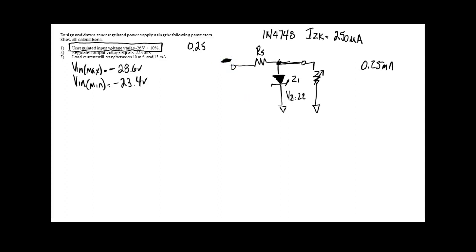To bias a diode, we need to put the negative toward the cathode. Well, here's the cathode right there, Brandon. So we're putting the negative toward the anode, so it's what? It's reverse bias. If we're using it in a positive power supply, we put the cathode toward the positive. Okay, you'll understand that.